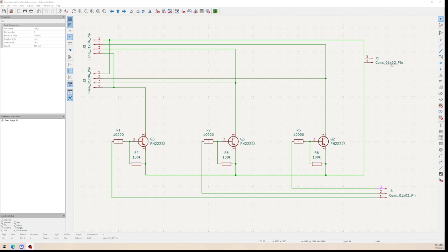Again, this is built in such a way that these boxes are kind of self-sustaining. I've tried to identify ways to get each one of these signals, meaning your power, ground, and your RGB signals, within each area of the car. The reason there are 2 parallel ports here is because one port, for instance, is the window switch and one port is the door lock, but they can be anything you so choose.